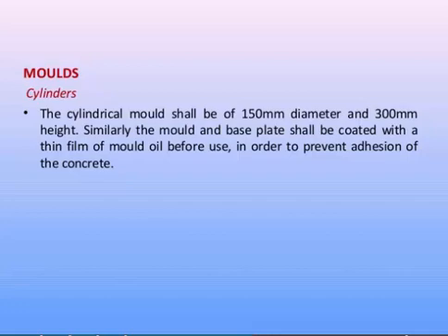The water or the solution in which the specimens are kept should be renewed every 7 days and should be maintained at a temperature of 27 degrees plus or minus 2 degrees Celsius. For design purposes, the specimen cured for 28 days shall be kept under observation. So this is basically how the molds are placed and prepared, and after that they are made ready for placing into the testing machine and getting the results.